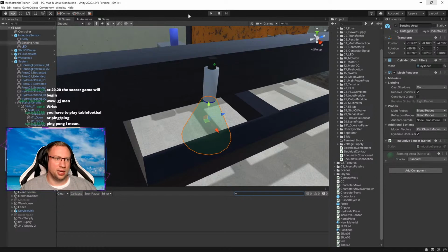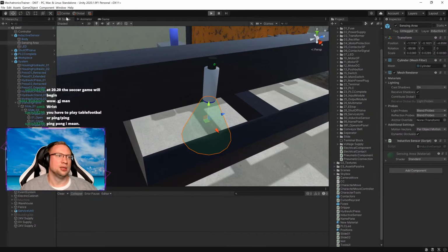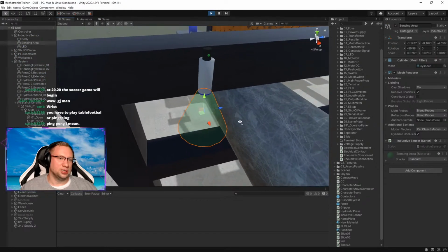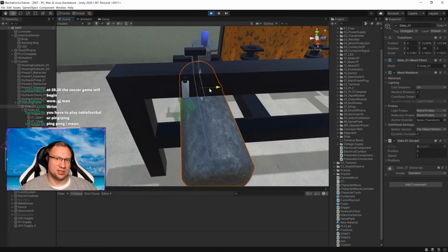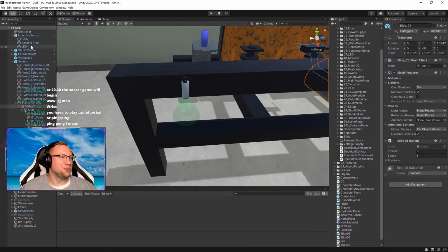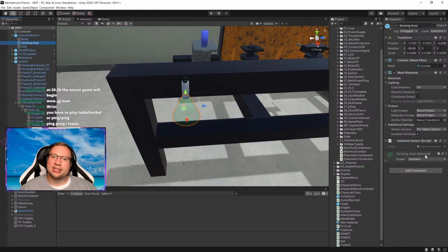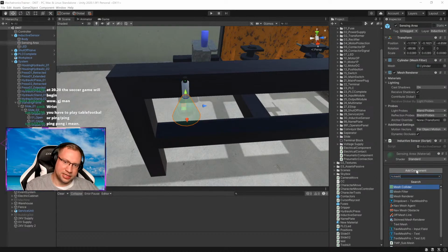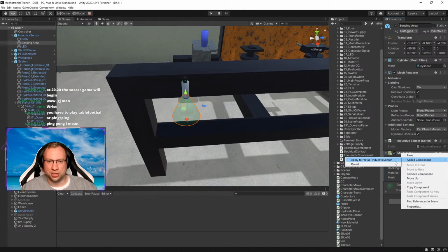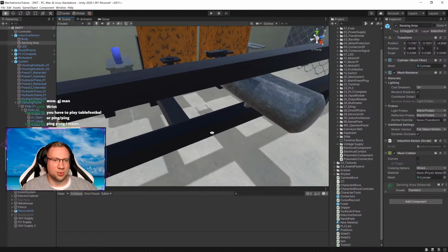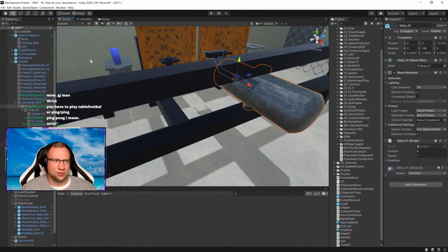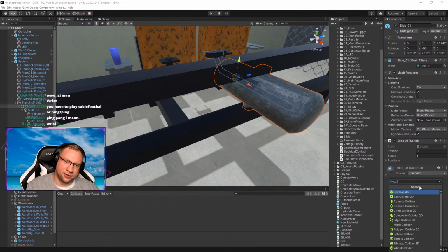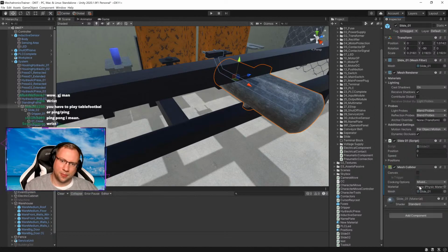So, okay, now what I can actually do is play this thing, and then once this gets there in front of it, oh, my script doesn't trigger. One problem: this thing does not have a collider. A mesh needs a collider to detect the collision, of course. So does the other one there. You don't have a collider. You need a collider. Mesh collider. Okay.